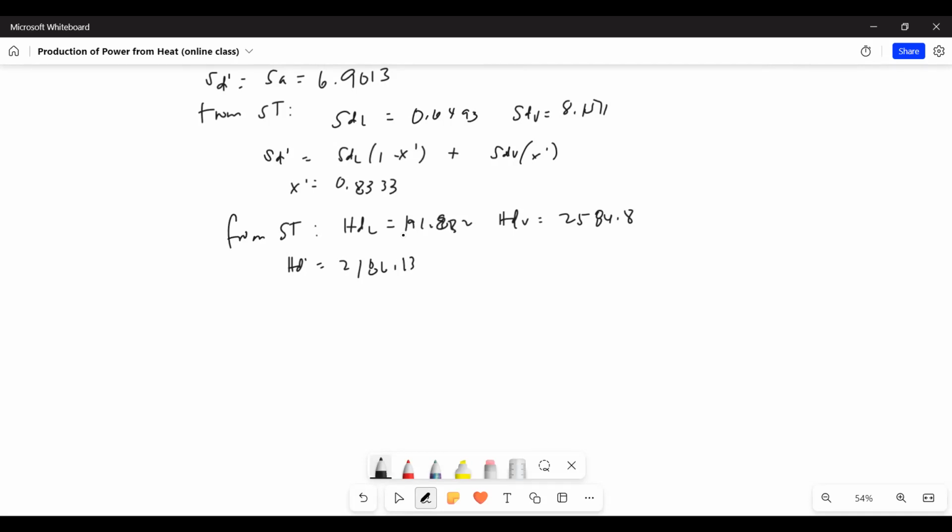So we got HD prime, and using the given turbine efficiency of 80%, we solve for HD. So what's the equation? Efficiency equal to delta H over delta H sub S. For the efficiency of the turbine, remember, the ideal delta H is below the fraction, so it's the denominator. So we have delta HS, which for the turbine is HA.